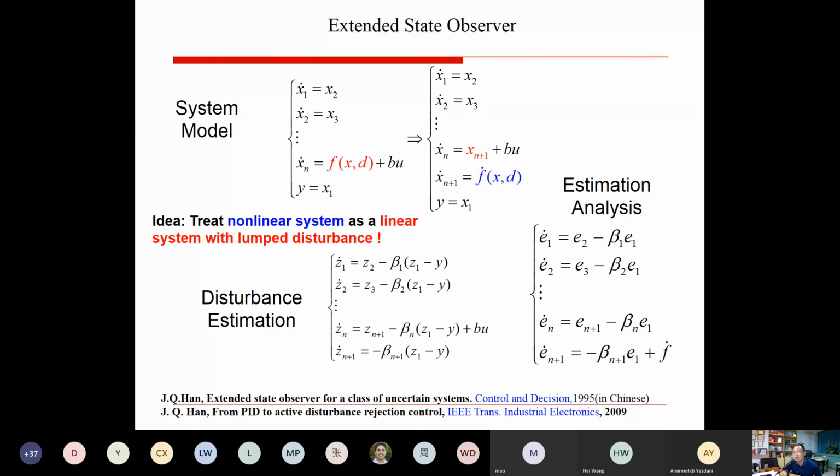And if there is backlash, maybe in the step response you can see the speed increase, in the middle stage it will decrease, then it will increase again. Maybe you will find backlash in the test. Then you should consider backlash. So it is different according to the machine, but you should put much time into system analysis and modeling. If you have a good knowledge of the system, then you can find how to handle it.